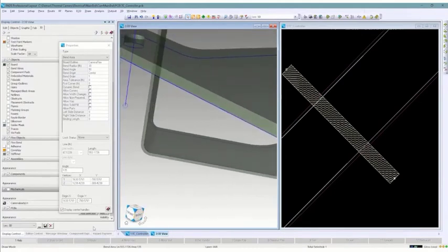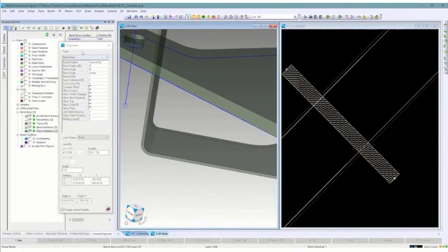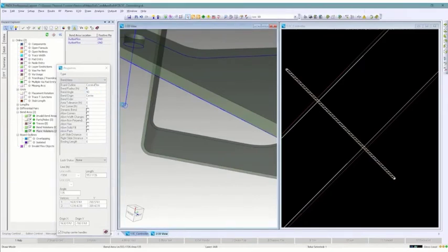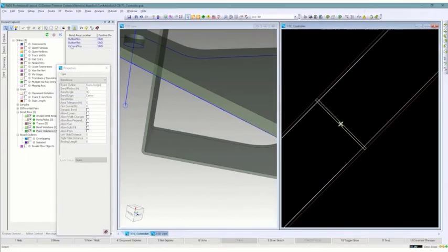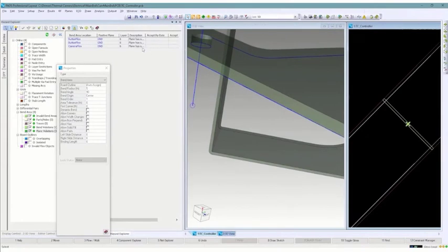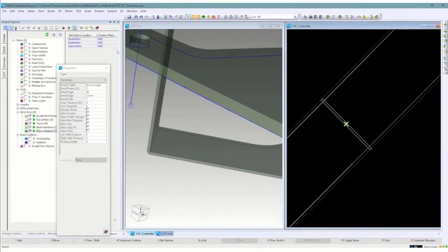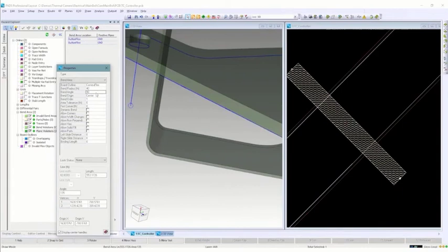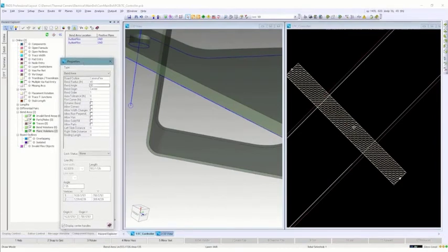Obviously, if that was too tight of a bend area, we would get a hazard telling us that the bend area is too tight based on the thickness of the flex and whether it's dynamic or not, based on our rules up there. So if we go to like 5, and I deselect that, we'll see there's our violation popped up letting us know that our bend area is too abrupt for that area. This is part of the dynamic verification that the tool is going to do for you, and it's even shown an error marker here that mechanical tools don't do, and a lot of general PCB applications do not do for you.